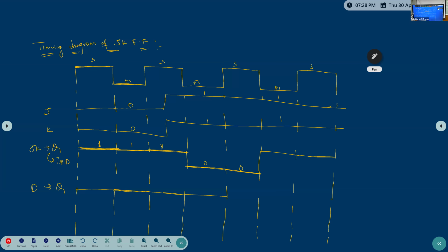Getting? So next, what happened? Slave will be turned on. In this condition, slave turned on. What is the value? 0. So then it will switch to 0. Next, off mode means the same thing it will maintain. So next slave will be turned on. In this condition, it is 1. So then it will switch to 1. So next condition it will be off, right? So it will maintain the hold.